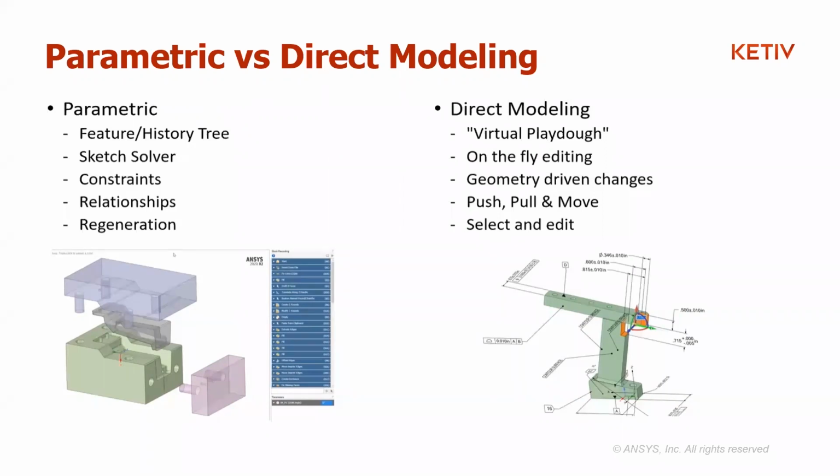So in a way, you need to know, okay, what does my final product look like? And what are the constraints that need to be put into place in order to get the final product? The good thing about parametric modeling or a feature-based or history tree-based modeling is that because the intermediate steps are recorded, you can see whichever steps you performed to create the final geometry, they're already there in the tree. You can go back to any particular step and then perhaps change a dimension, change a value, and then go down the list again.